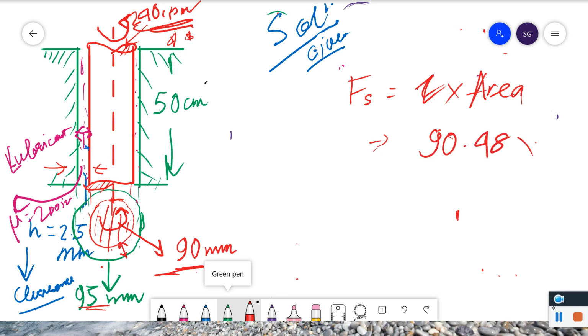And area, it is area. Now imagine what will be the area. This cylinder is just covering the fluid, so its CSA, curved surface area, will be the area, since only its outer surface is in contact. The outer surface of the cylinder is in contact, not the inner surface. So it is just CSA, not TSA, because the upper surface is also not in contact. So the curved surface area will be the area here.